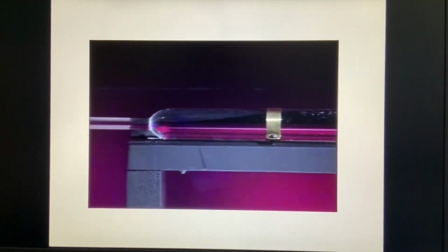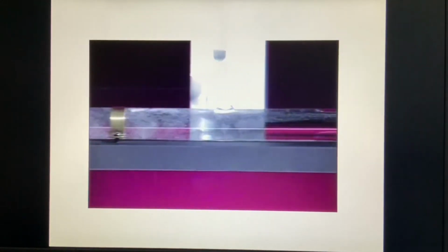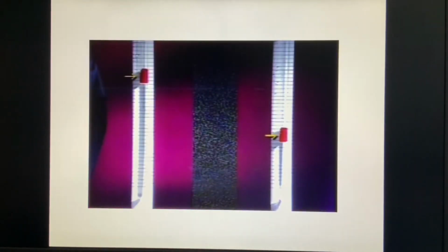Water flows through this horizontal glass tube, which has a large diameter at the beginning and end, but a constriction in the middle. The pressure in each of the sections is indicated by the water level in the vertical tubes. The two outer vertical tubes show the pressure drop that occurs along the horizontal tube. The center tube is covered.